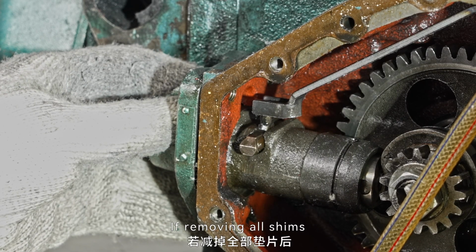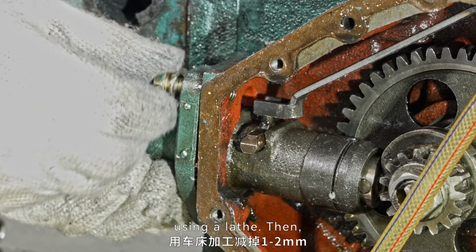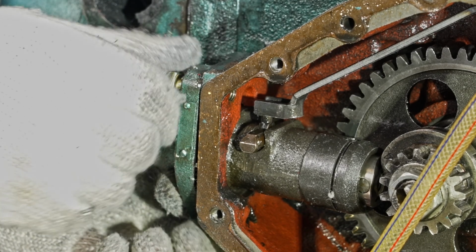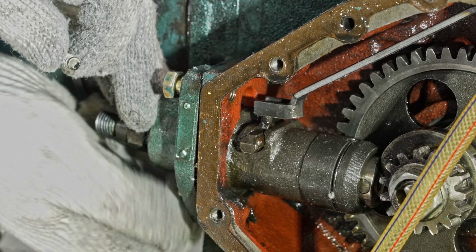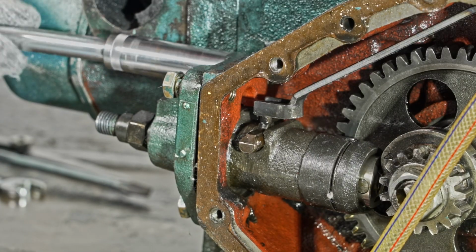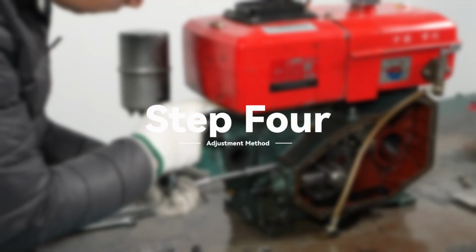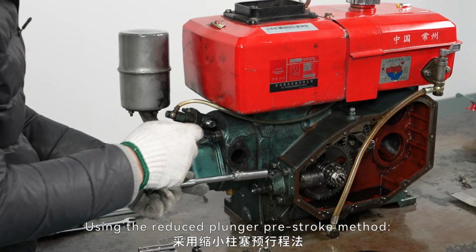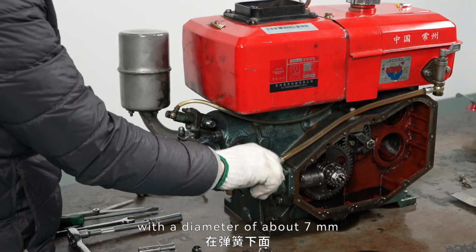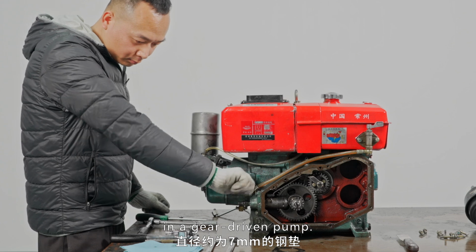If removing all shims still results in late fuel injection timing, machine 1 to 2 mm off the shim using a lathe. Then, use shims to adjust the timing to the correct value. Using the reduced plunger pre-stroke method, remove the roller body and add a steel shim with a diameter of about 7 mm between the spring and the end of the plunger in a gear-driven pump.